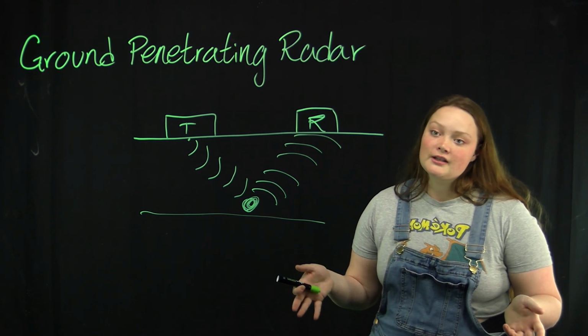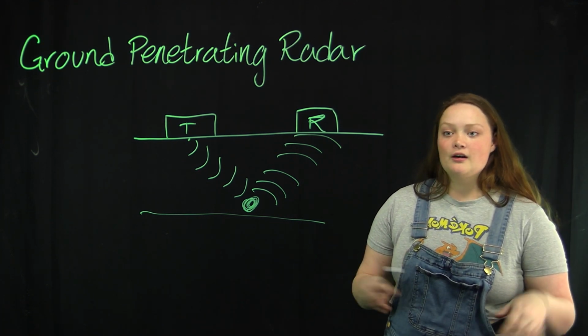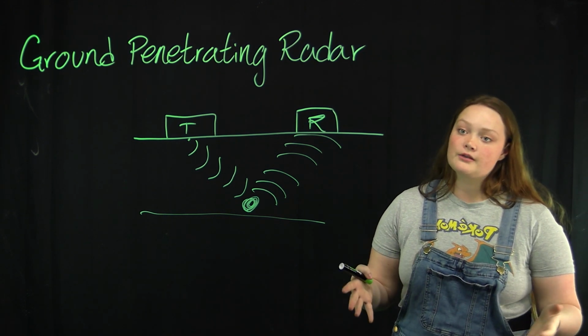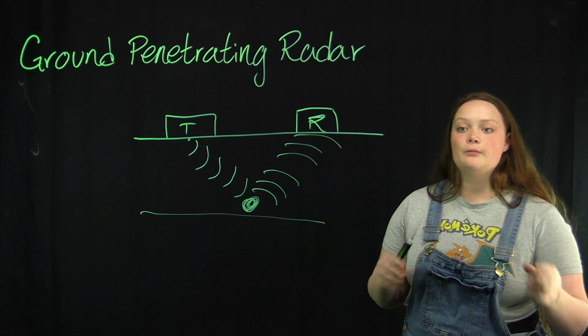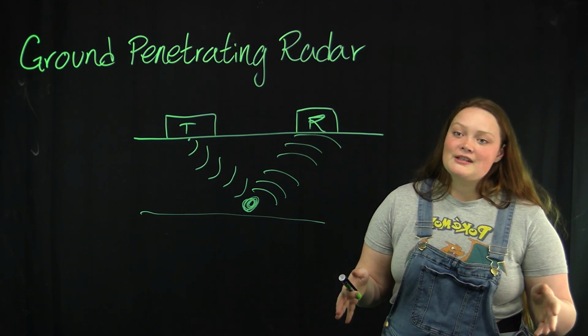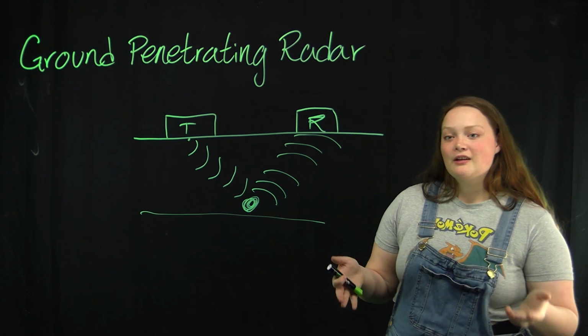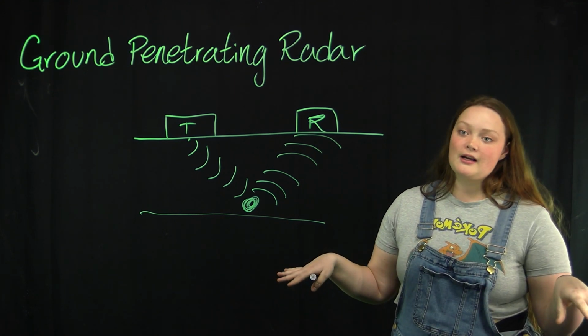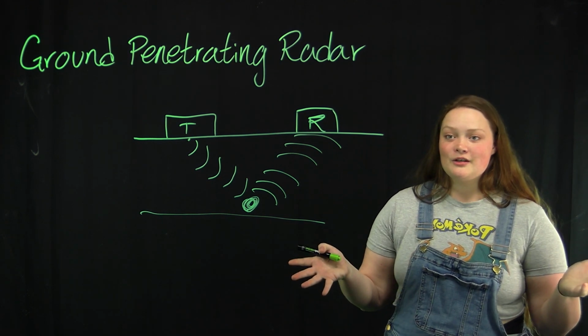So in construction, we can use ground-penetrating radar to go over the ground and sense any kind of sensitive materials like rebar, because rebar is going to be super conductive, so we'll be able to see that difference once we start imaging. As you guys will see, we're also going to be trying to find sprinkler lines, because the water is going to be more conductive than the rest of the surrounding area. So that is GPR.